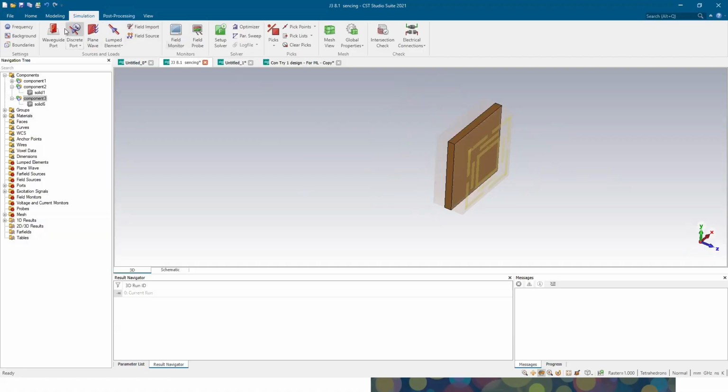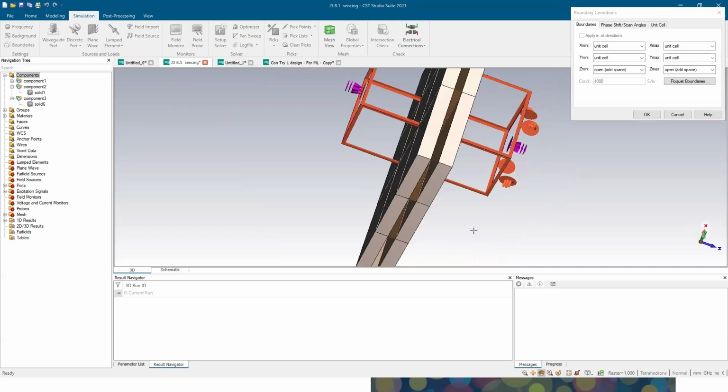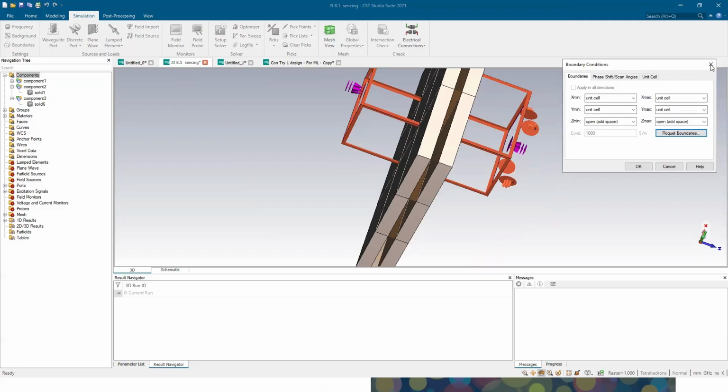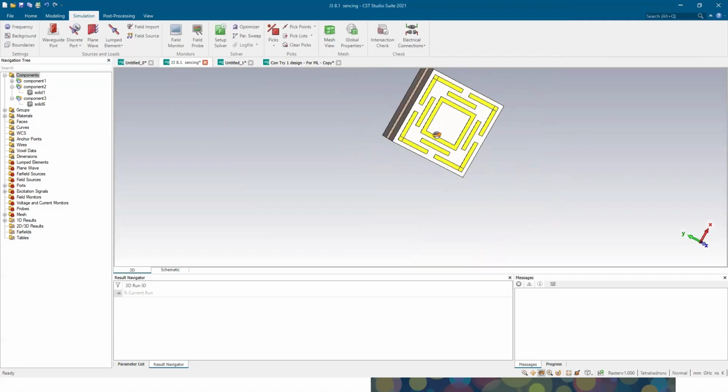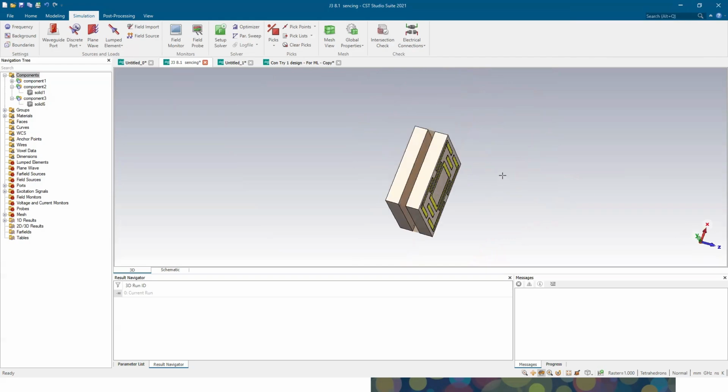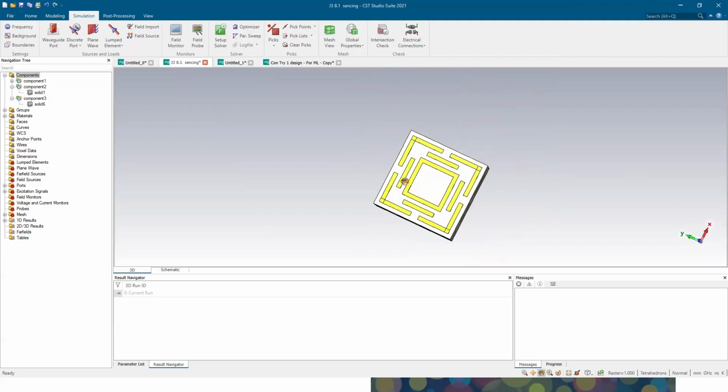You can see the simulation setup is pretty much the same. We used boundary conditions, and everything is the same. Here you can see that we used two ports. Why did we do that? Because we are planning to measure in transmission and reflection mode. I will show you those things later on. Okay, just a side note.